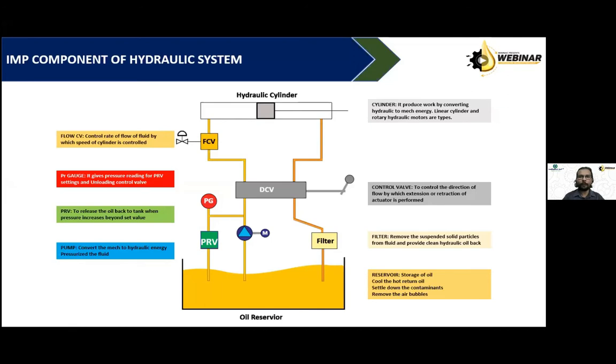So the component we saw in the poll result that causes much trouble is, first, the hydraulic pump, the very first component. If we see in this diagram itself, we have not mentioned any suction filter here before the pump, or suction strainer. The very first mistake we do in our hydraulic circuit.